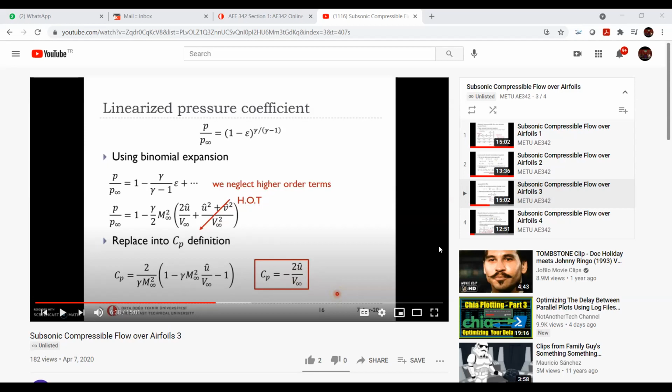In fact, we took it further to obtain an expression for the pressure coefficient distribution on an airfoil like that. Of course, it needs to be a thin airfoil, because we limit the solution of this equation to small perturbations. The airfoil should be thin, so it's not going to disturb the flow a lot, meaning it's not going to generate high magnitude changes in velocity components or pressure.